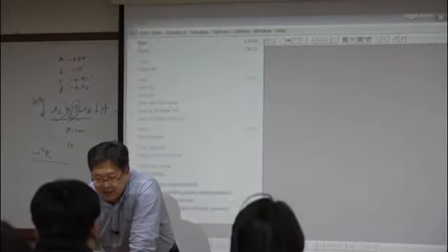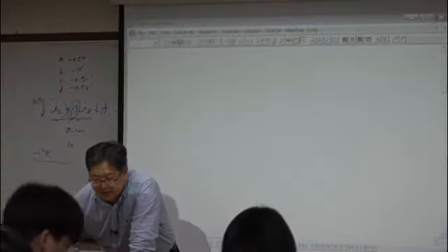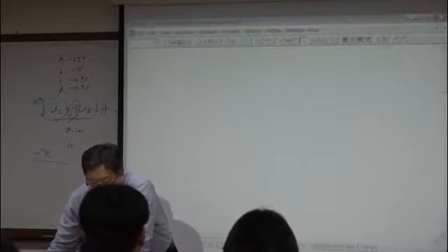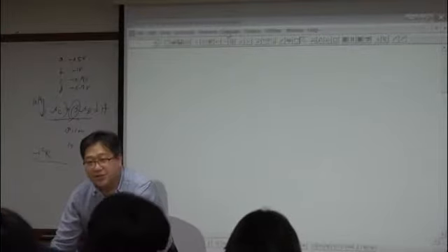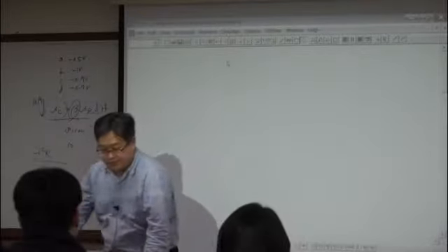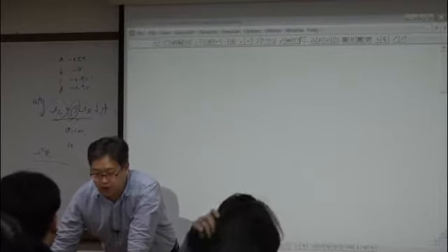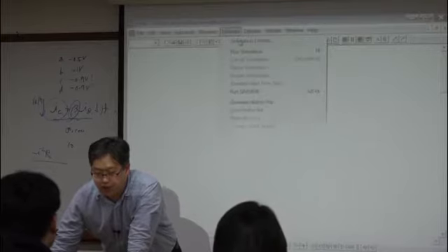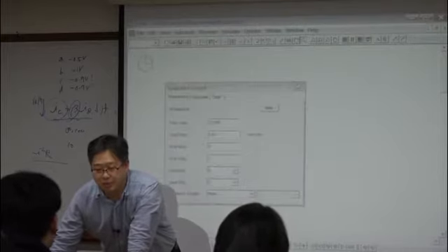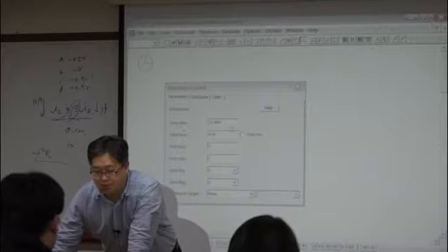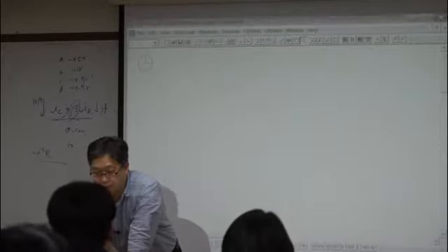And okay, for PSIM, to simulate the circuit with the PSIM model, first you should have the simulation controller here. So you can bring the simulation controller below. The symbol looks like a clock. Now the time step is just 10 microsecond and total time is 10 milliseconds.